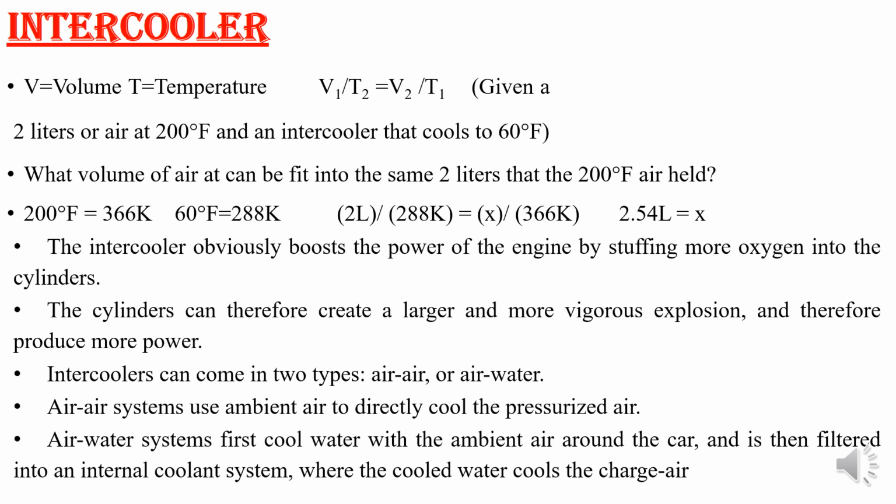It is the basic concept of supercharging. A turbo works on the exhaust gas, and the compressor compresses the air, so it takes some time. That time is known as spooling time, and that is your turbocharger lag. So that is about turbocharger lag.